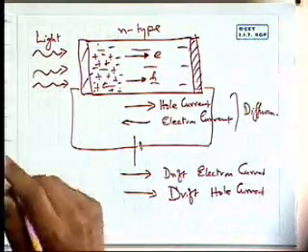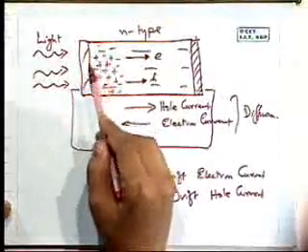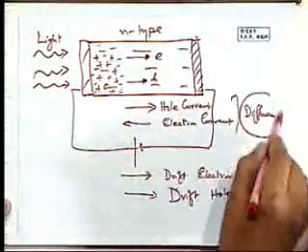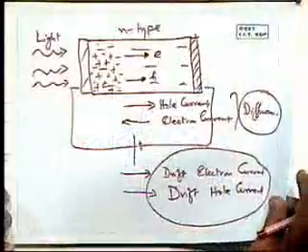Okay? As somebody mentioned the photoelectric word there, in some kinds of devices where I'm not creating some artificially doped situation as we did here, where I'm not able to maintain the gradient, once it starts flowing and it establishes equilibrium, there is nothing more to it. But here we see that as long as the light is on, electron-hole pairs are getting generated, and in that case, these diffusional currents could be significant. So in our solar cell kind of behavior, where light falls, we have to worry about both these currents, diffusional as well as the drift current.